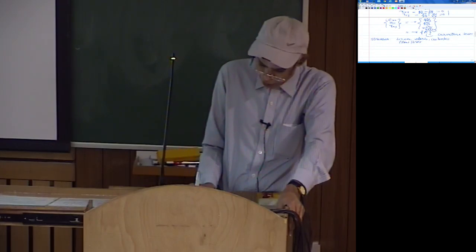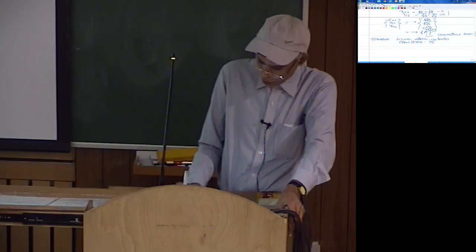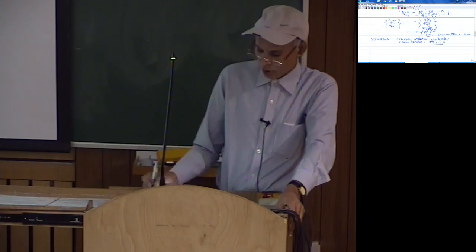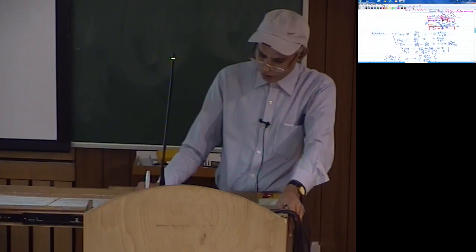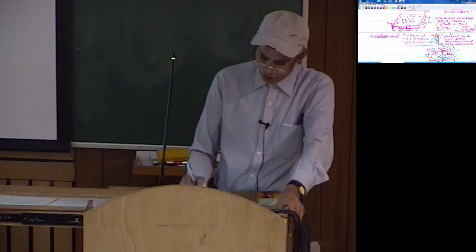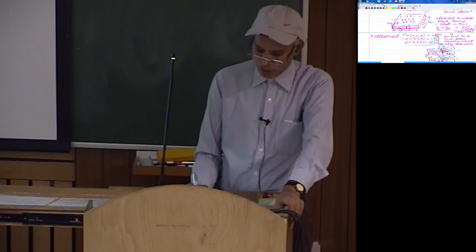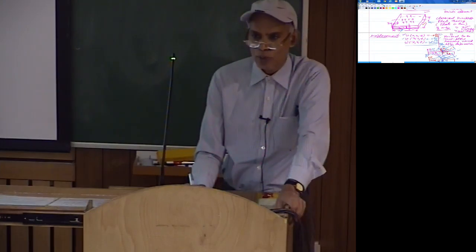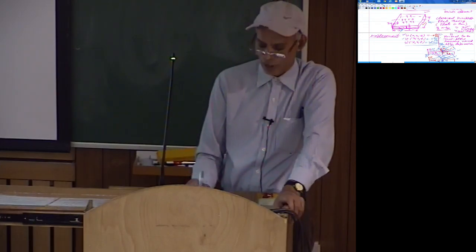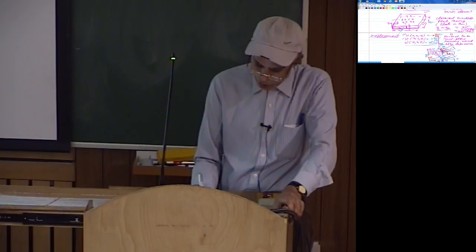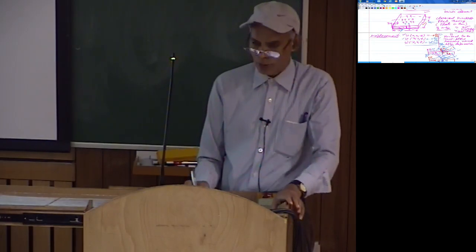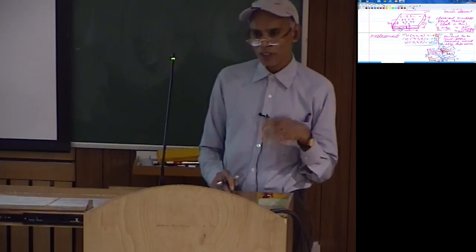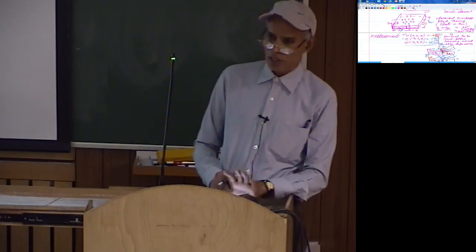Plane stress here means we are going to say that sigma zz is 0. So in a plate under a transverse load, sigma zz is actually negligible compared to sigma xx, sigma yy and tau xy. Although if there is a distributed transverse load, on the surface where the load is there, sigma zz would actually be equal to the intensity of the load.